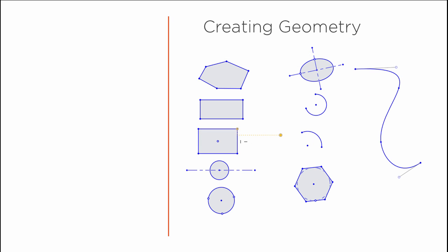Now when you start creating geometry, here's a few examples. You have blue lines, you have dots which mark corners, and you have what's called a region when your lines of geometry are enclosed, or a profile. Sometimes it happens that the lines and dots are very, very close but really don't touch each other, and then you might think there's an error. It's almost always the case that the lines and points don't touch 100% when you don't see a gray region.